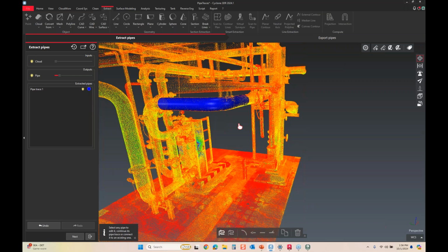When we scan, we want those same locations in our scan, whether we set a target up over them or, and I don't like to do this, we create a virtual target on the actual survey pin.